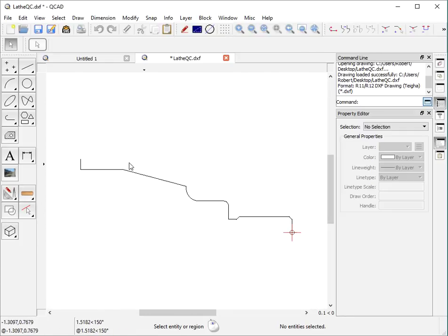Now what we've got to do is add a polyline up here to start the roughing passes. What this will do is establish the roughing passes. Then we'll establish, well, first of all, we'll establish the offset for the finish roughing pass. So let's do that now.